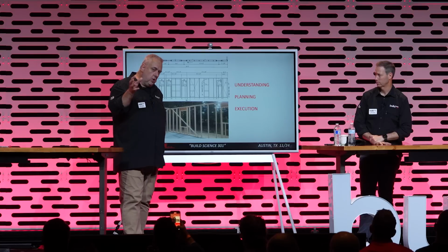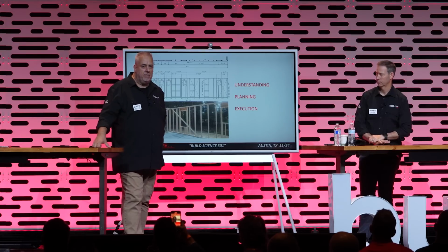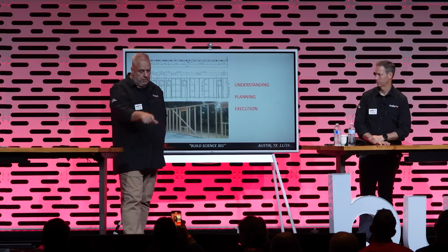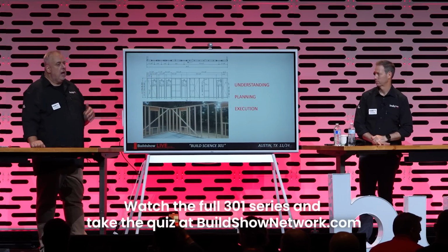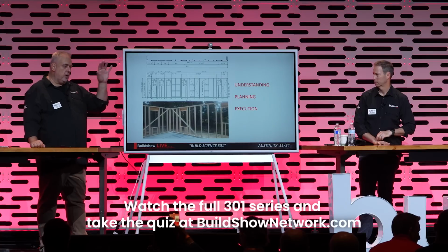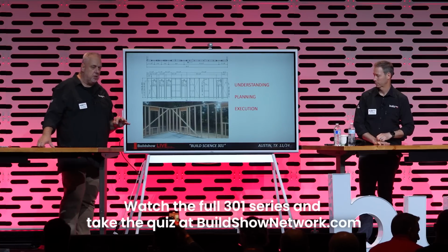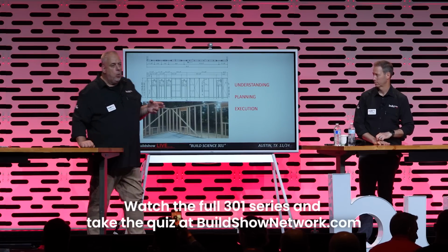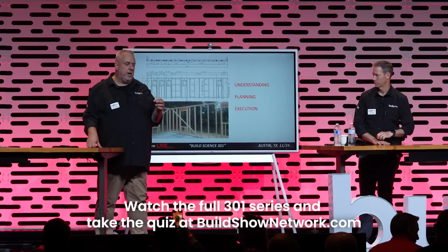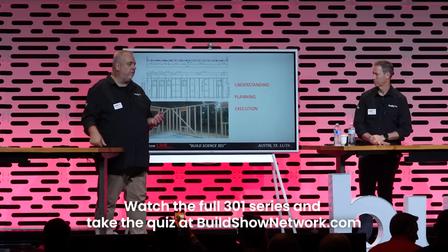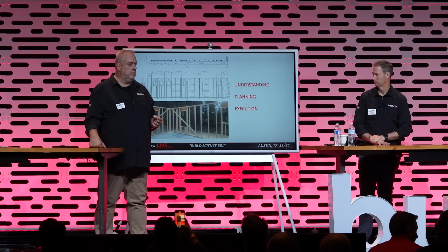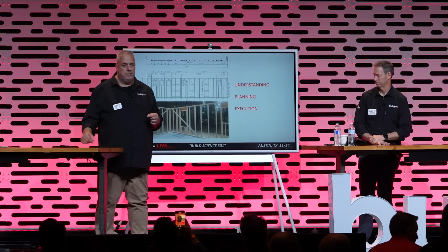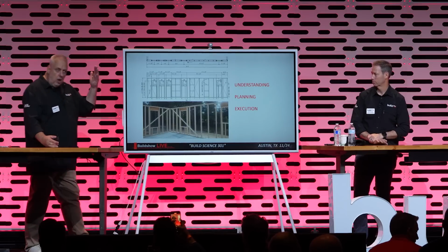For 15 to 18% of the wall, we have the opaque area that is the framing member that you see here. So if we gang those all up, it accounts for 15 to 18%. If we normalize those R values across those 3 situations, you'll come to realize R32 with a domestic R3 window is probably somewhere around R14 for a whole wall R value, right? It's not R32. It's R32 in the center of cavity, but that only exists for 65% of the time, right? So just a little education.